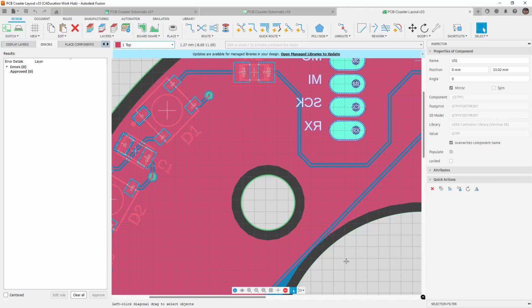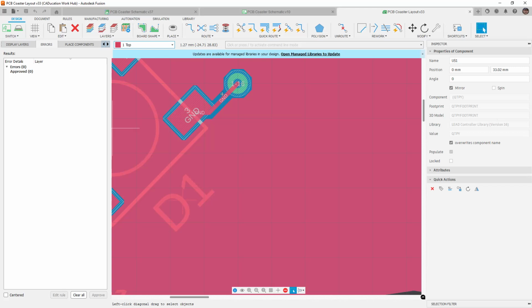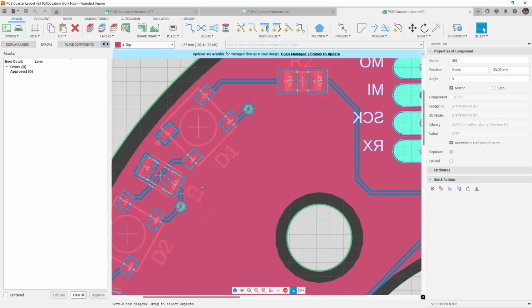This is an area of copper that is connecting the top layer and the bottom layer. So when you take a look closely at your boards, you want to make sure that things like the ground pad is isolated from the polygon pour on the top. If that's not true, then you're going to end up getting power and ground connected directly.